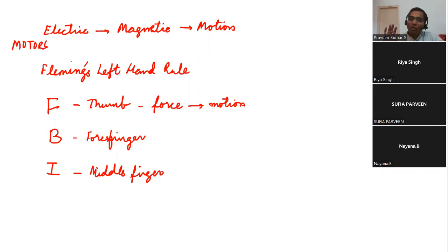So to move forward, there is a force applied in the forward direction. So you will get to know that if the train has to move forward, the current has to flow from my right side to the left side. The magnetic field should be pointed in the upward direction. So this will tell you how the trains will move forward.